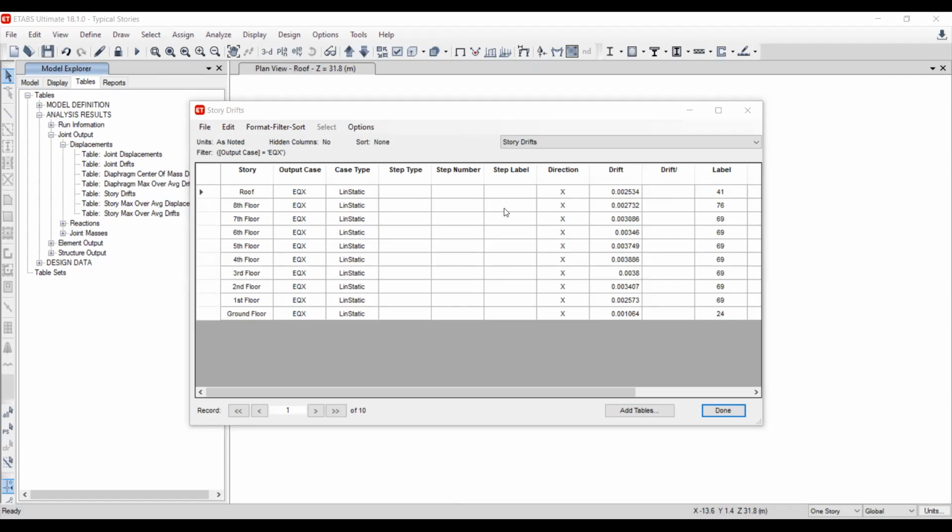You can multiply this by 0.7 and multiply it by 5.5. We can see the seismic load is within allowable. Why I multiply by 0.7 and 5.5? If you go to the code, what does it say? If it is in UBC 97, which I'm familiar with, if you go to UBC 97, if I'm not mistaken, you can go to page number 16.